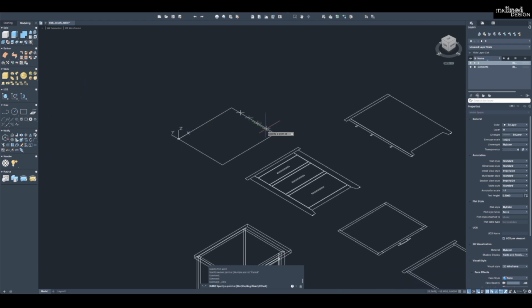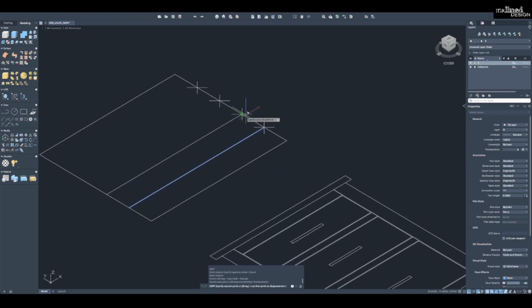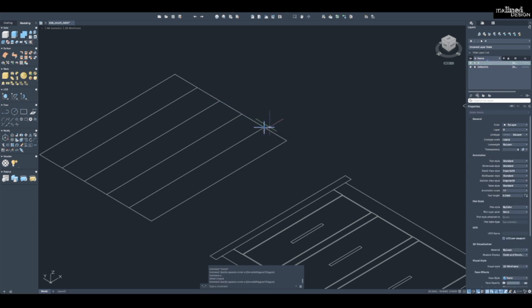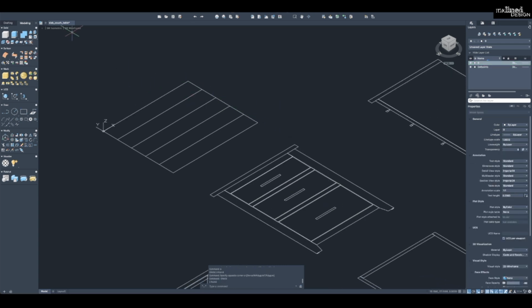So, and when we make this, what we will do is we will grab the construction line. So I hit L for line, enter, and then just going to go over like this. And you'd want to rotate the pieces, grain cupped up, cupped down. Then we can cross select those. I guess I didn't grab that. And again, we're going to use the press pull. And here we're just going to go up 1.